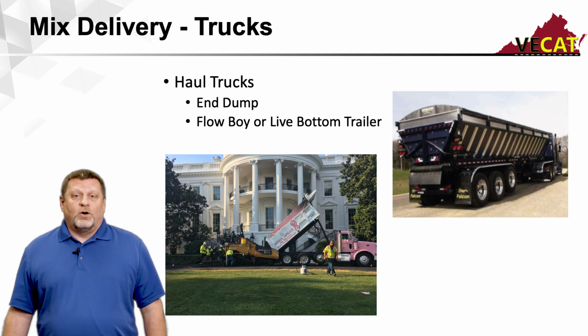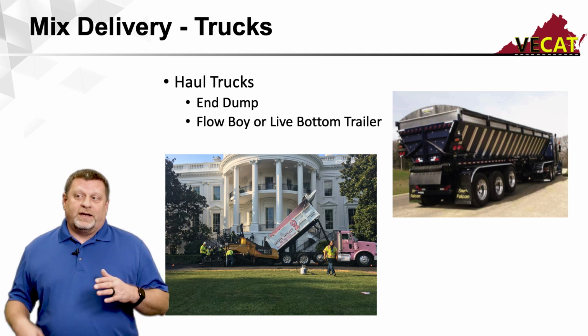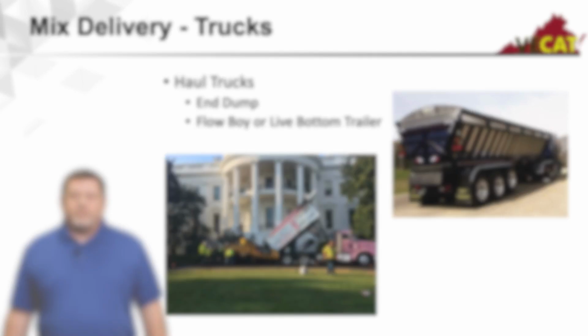So we use flow boys, and the way a flow boy works, the bottom of that trailer is a conveyor that transfers the mix backwards and deposits it out of the back of the truck into your paver hopper. But it does that without having to lift the bed.